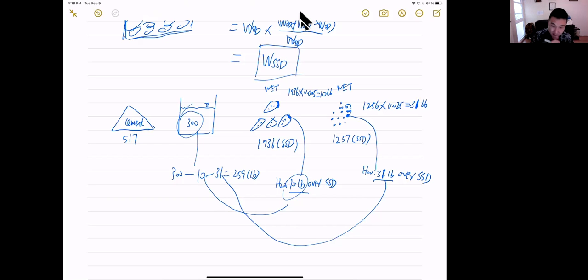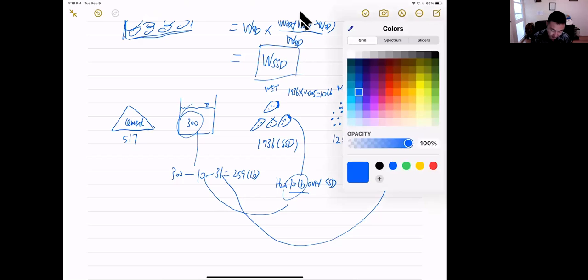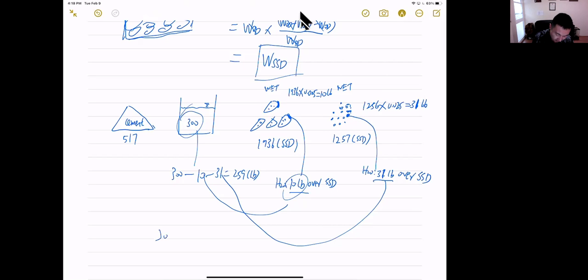The real amount of water is still 300 pounds, coming from 259 from tap water, 10 pounds from the gravel, and 31 pounds from the sand. We want to keep this 300 water unchanged, no matter what the moisture content is. That's why we need to do the adjustment.